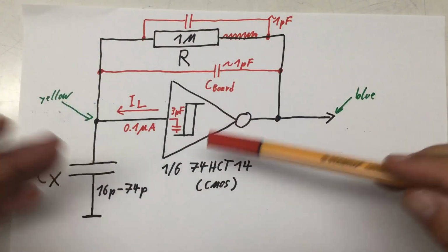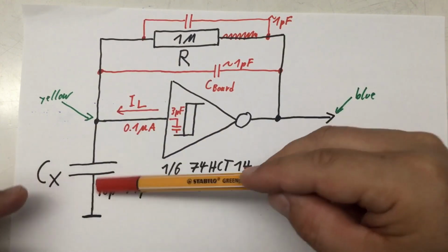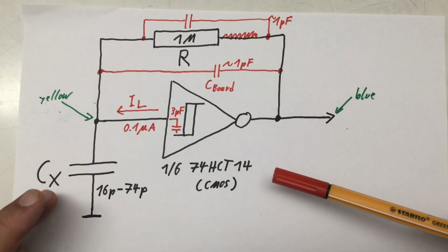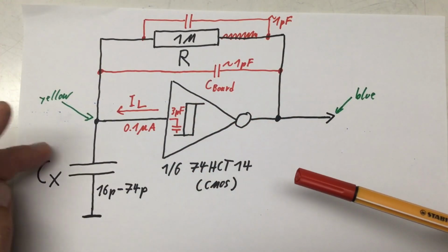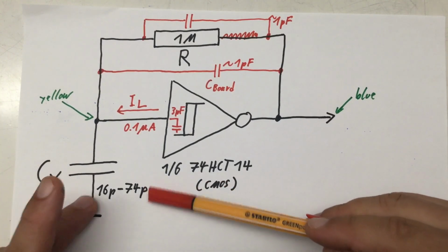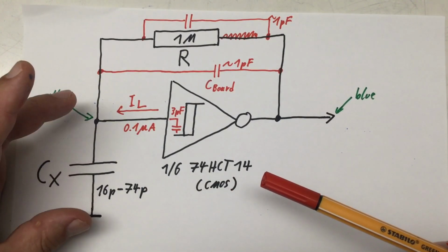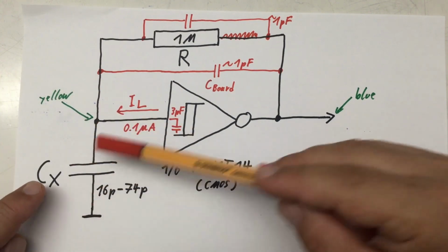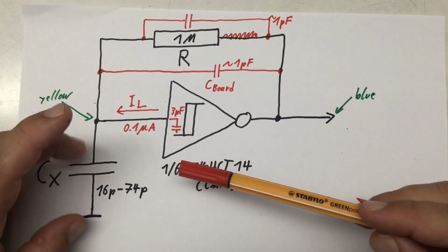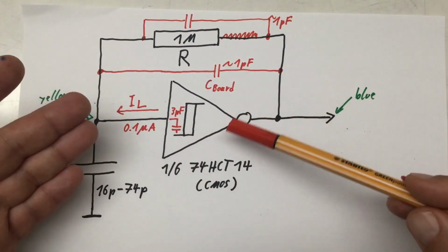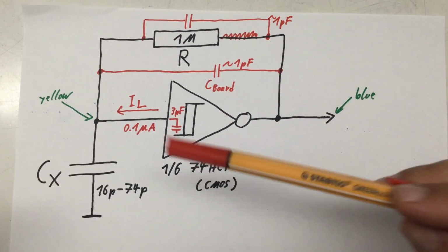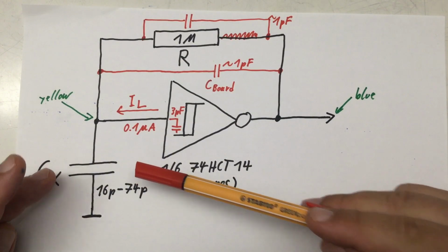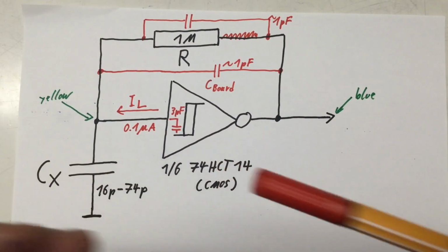All these parasitic capacitances here deliver approximately the same current spike into or out of our measured capacitor when we switch from charge to discharge and vice versa. However, since our measured capacity changes, the voltage jump we see across our capacitor changes in amplitude. And that totally messes up our nice relationship between output frequency and the measured capacity. Yeah. It is what it is.